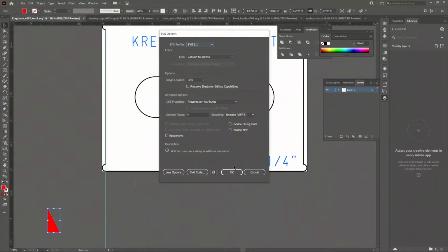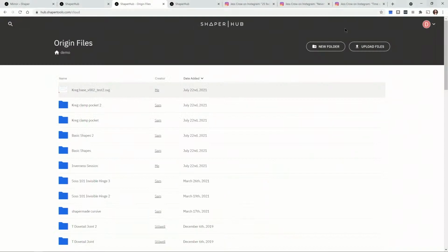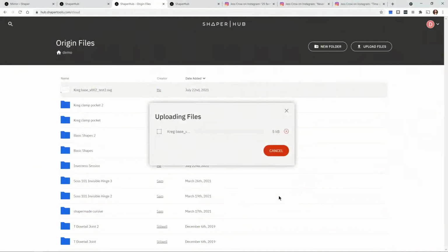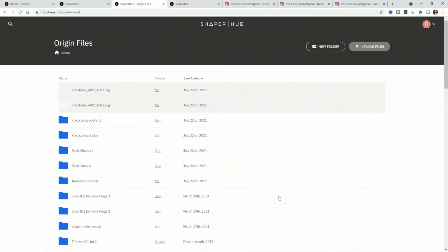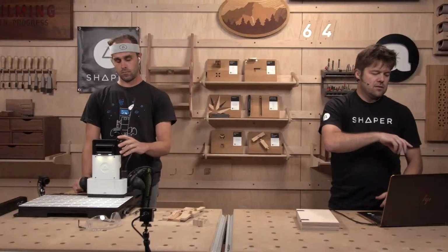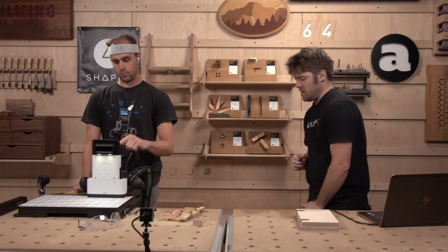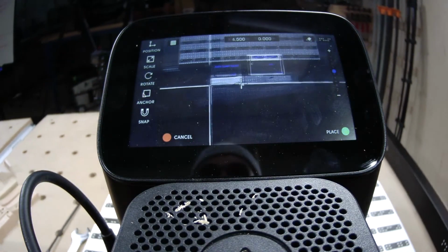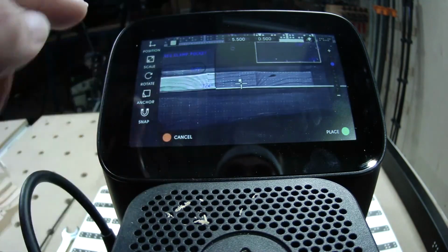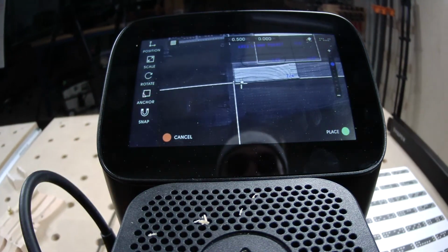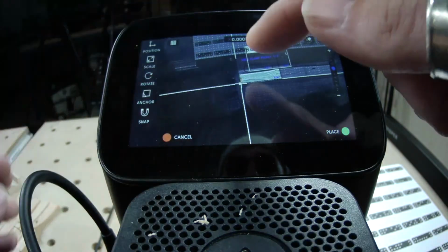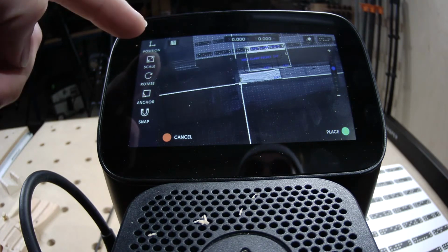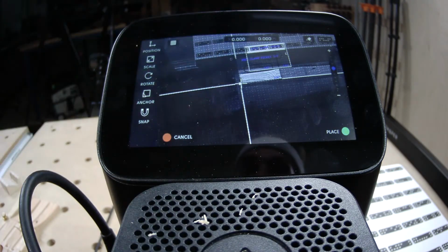And then we'll upload that using the same settings. Upload a file, test 3. So now what's going to be really interesting here is the bounding box of the object is not impacted by my offset there. And just like magic, anchor. Again, look at that. Okay, so now you can see that the dot is way outside of the shape. So if I go to the same location, 0, 0, that file's actually going to be offset from that. So this is a great way to bake in positional information into your file, even when you're using a grid on the edge of a material.